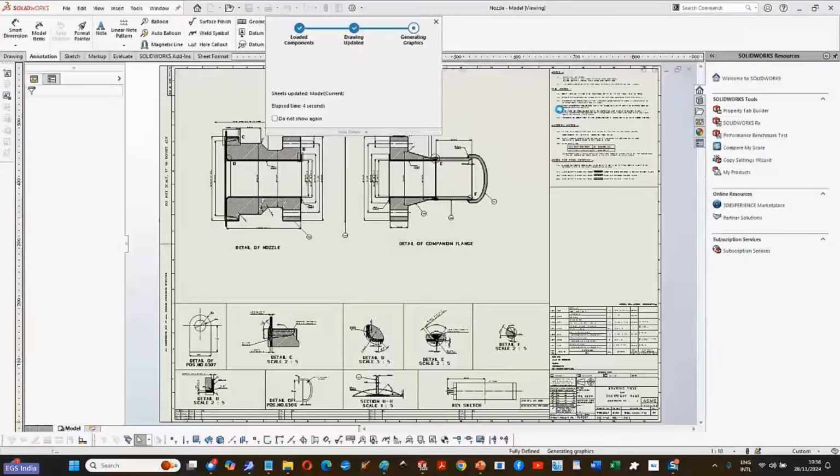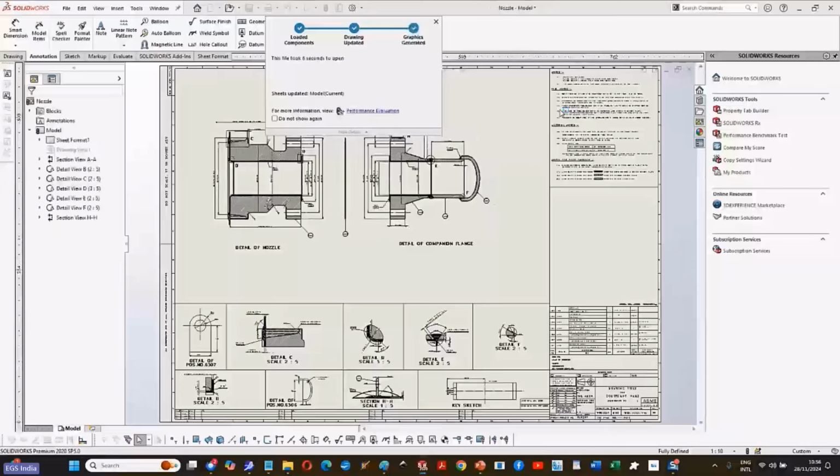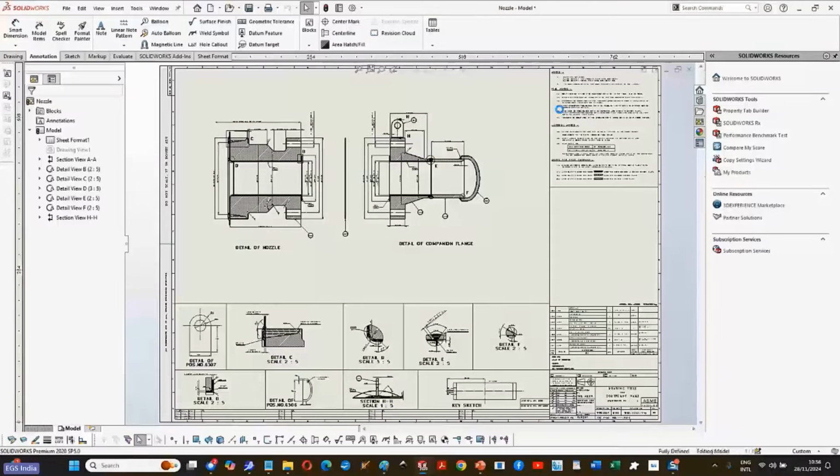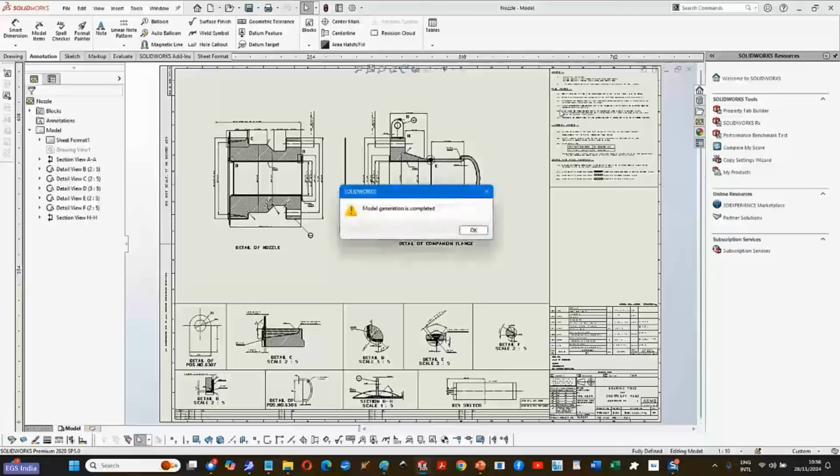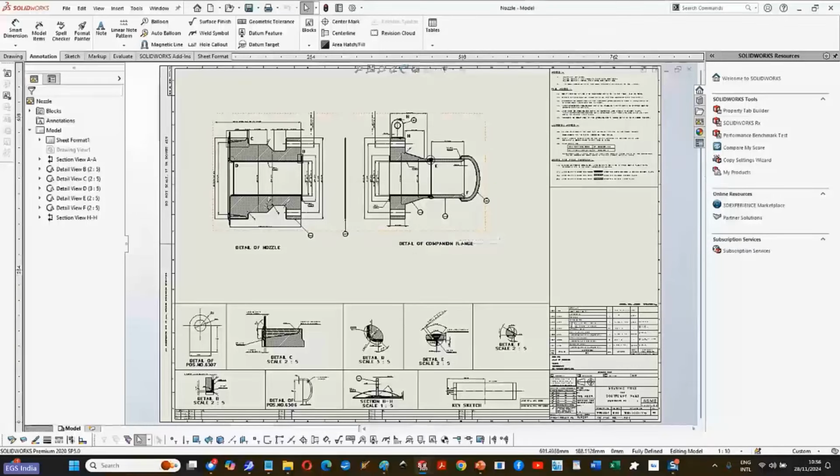The nozzle sections, the edge preparations and other things can be brought in from the sketches which are kept in the design library. You can bring it in, pull it, and put it over there. And every time those design sketches change, the drawings will change. No intervention is required. You put this together, you get to see the complete nozzle drawing coming out in one step without touching anything. And this was written using the SolidWorks macro.